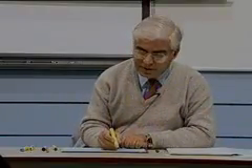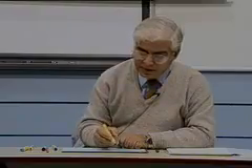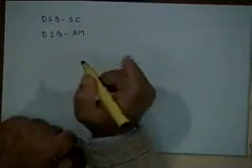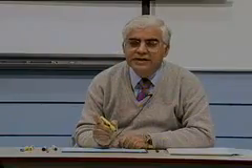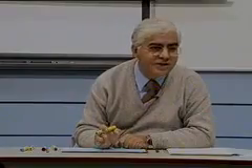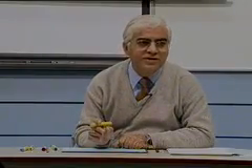So let me come back to the discussion regarding these two. One of the properties of the suppressed carrier DSB waveform, if you recollect, was in fact not a nice property. We said that it is a disadvantage of DSBSC that if your local carrier is out of phase with the incoming carrier, you will tend to lose the signal, right?